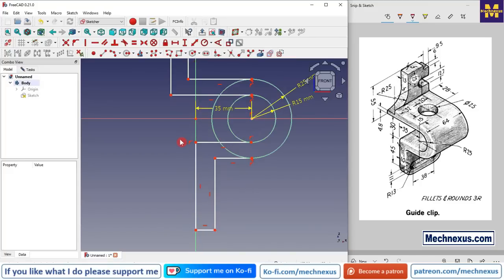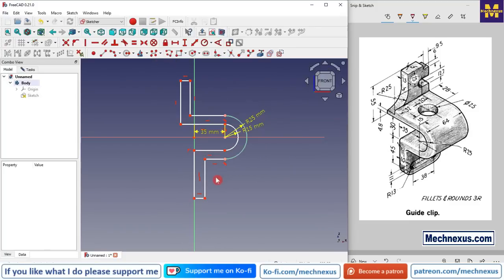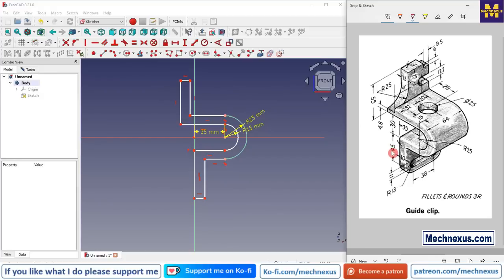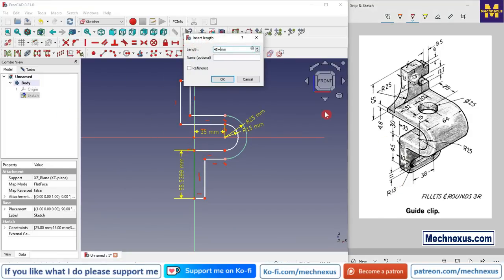And now the next thing which we will do is to trim the unnecessary geometry. So click on trim, trim the internal, and trim this arc as well. Now we will read the dimensions. So here we can see that this is 45 and this is the R13. So this outer radius R13 and this slot center are concentric. So 45 plus 13 from this edge. So we will select this edge and give 45 plus 13.